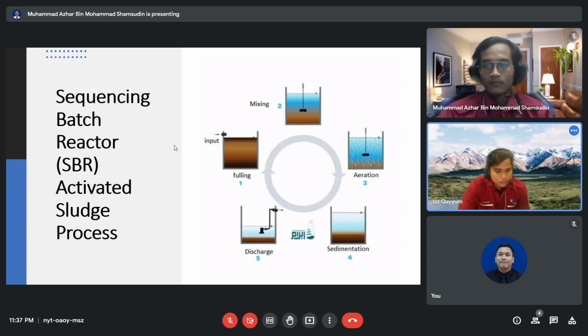Normally, the biomass concentration ranges between 2,500 and 4,500 mg per liter, with oxygen about 2 mg per liter. With aeration time up to 24 hours, the oxygen demand can be reduced by up to 99%. According to the different oxygen demand, biological treatment methods can be divided into aerobic and anaerobic treatment. Because of the high efficiency and wide application of aerobic biological treatment, it naturally becomes the mainstream of biological treatment.